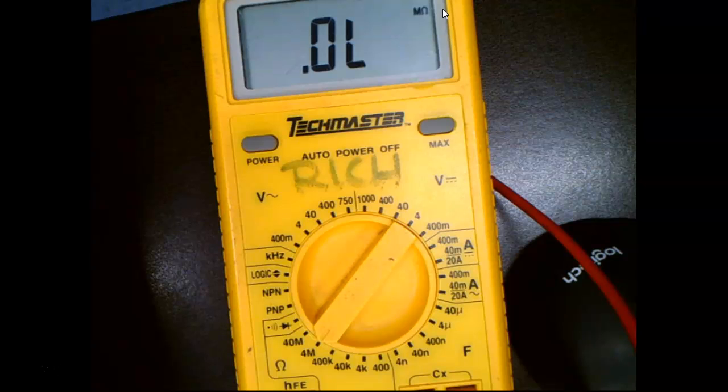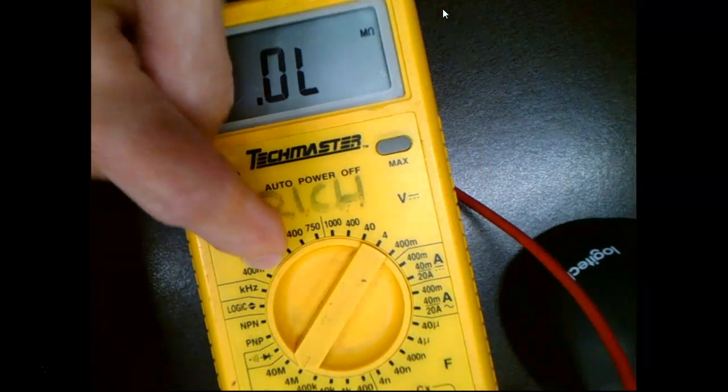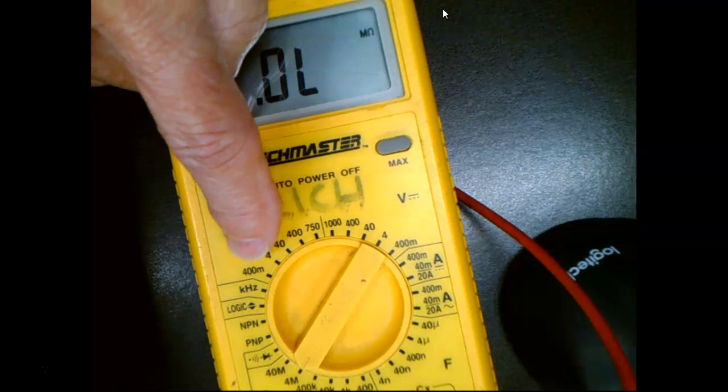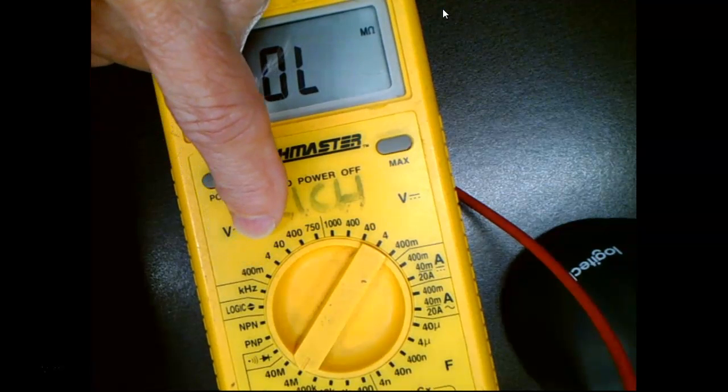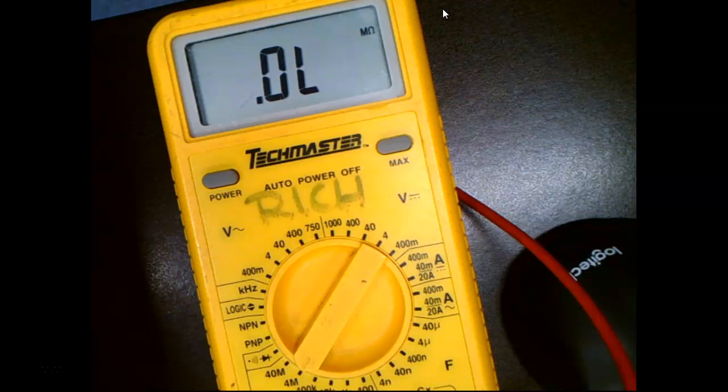So if I've got a 2,000 count meter, when it gets up to 199 ohms, then it's going to go to 0.2K, which is actually 200 ohms. This is a 4,000 count meter. How do I know it's a 4,000 count meter? Because all my ranges are in fours. And then we have 6,000 count meters, which are very expensive. Your cheaper ones are going to be 2,000 count meters, because all your ranges are going to be twos. If it's an auto ranging meter, it's going to range on 199, right? You understand that?